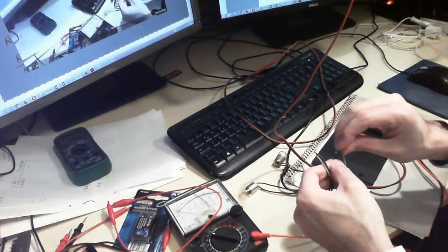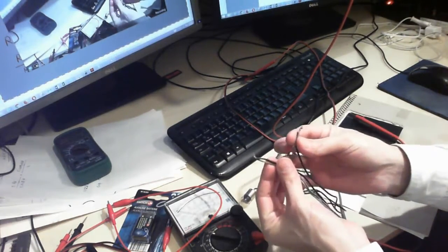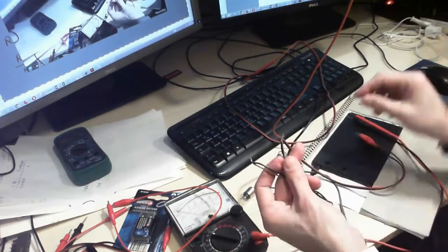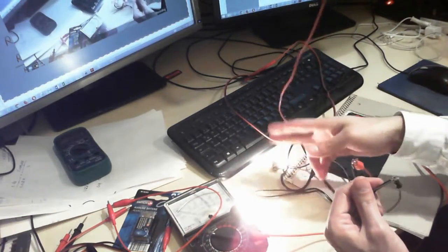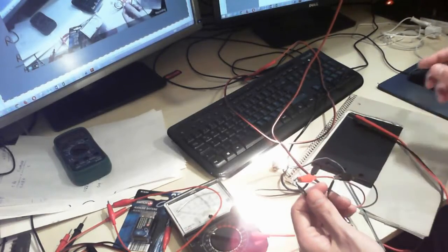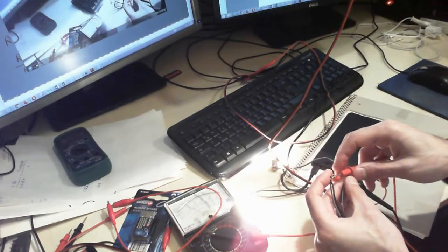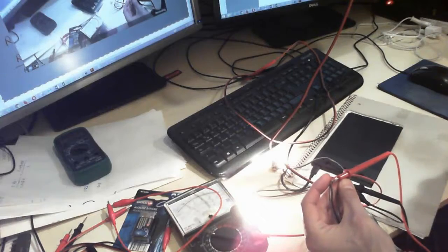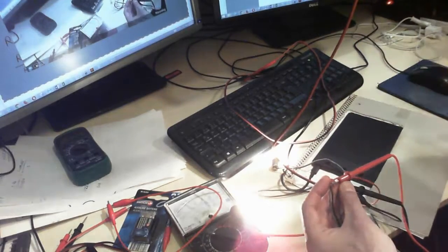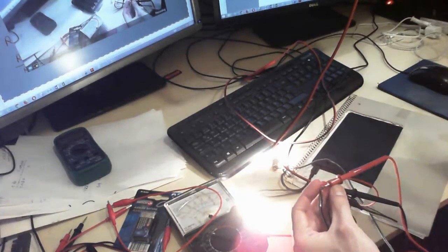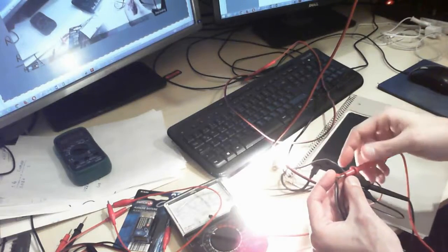Now let me connect them in parallel. I'm not connecting them in series, but in parallel, meaning that the two lamps are simply connected together end to end. And if I connect my power supply to them, you can see that they are a lot brighter than before. So this is in parallel. And right now, even the voltage is around 10 volts, meaning that this power supply has some problem. When there is load on it, the voltage decreases a little bit. So I increase the power on this to get it back to 12 volts, and you see that the lamps are very, very bright, right?